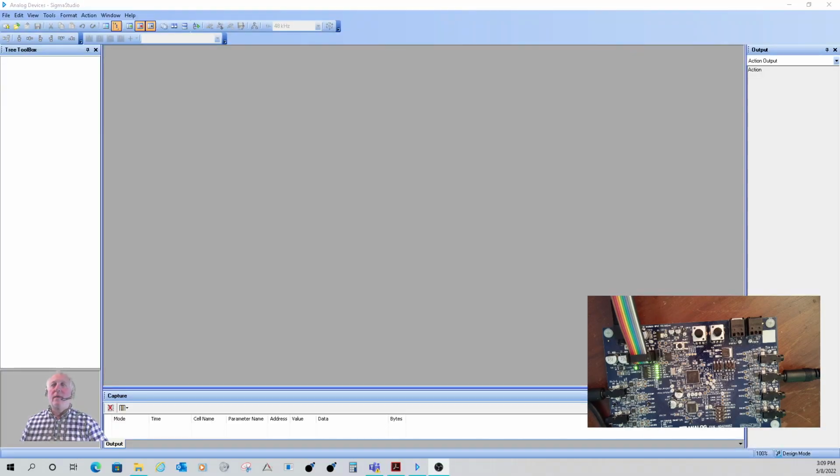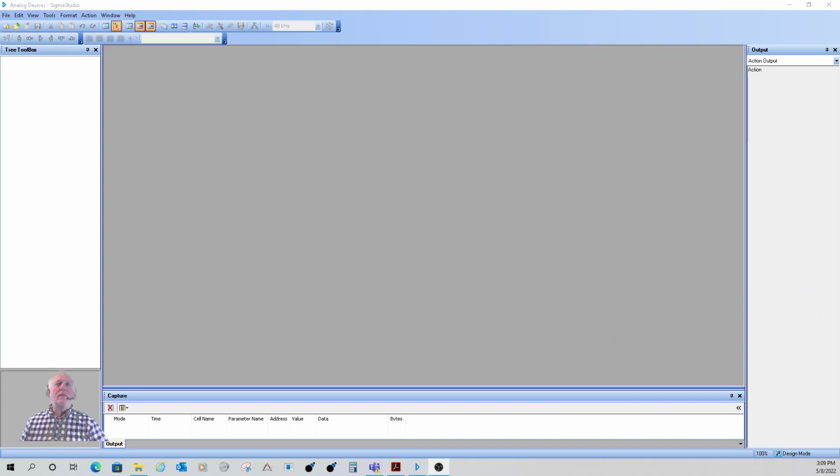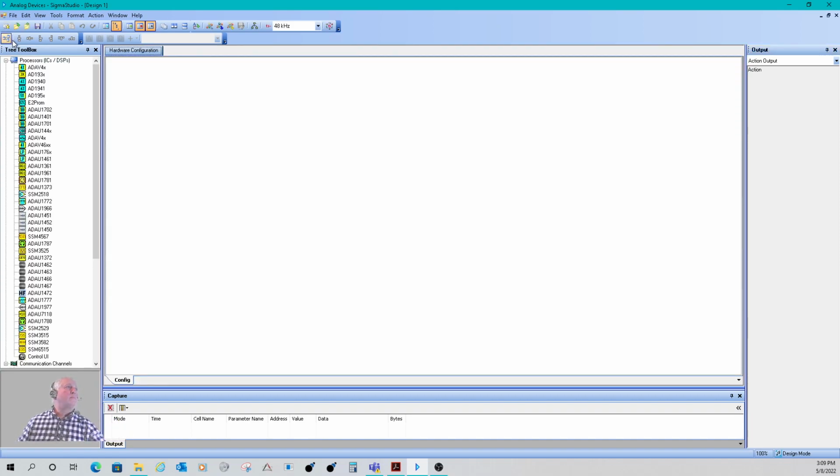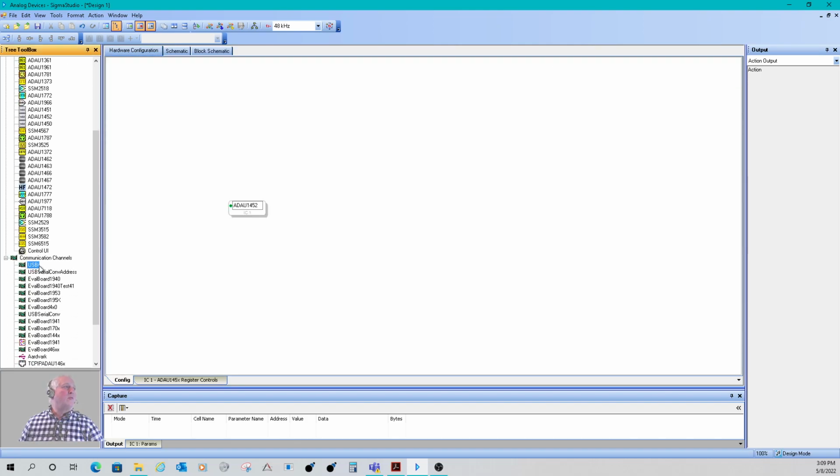Let's start a project. Go over here to the new projects and 1452. I'll drag one of those in. Don't slow down on me now, Mr. Computer. And then I'll drag in a USB-I and hook that up. Set up the SPI. That's fine. That's what this eval board is for.